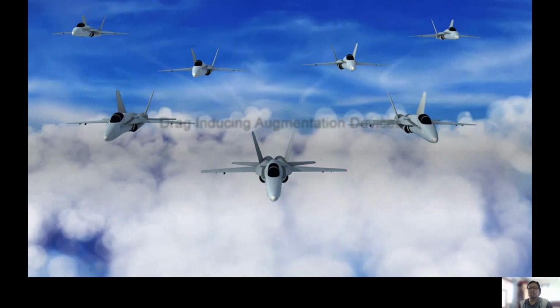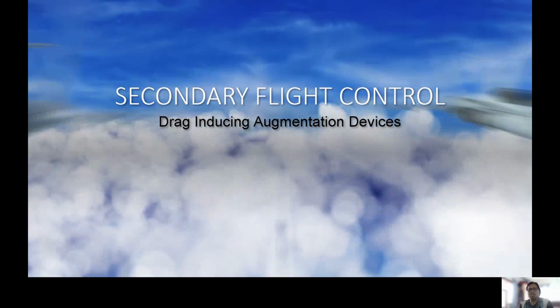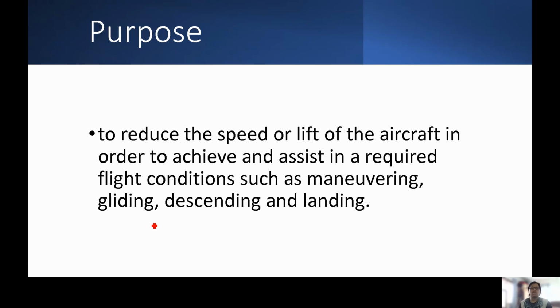So we move on to the next secondary flight control devices, which is drag-inducing augmentation devices. The purpose of these devices is to reduce the speed or lift of the aircraft in order to achieve and assist in a required flight condition, such as maneuvering, gliding, descending, and landing.